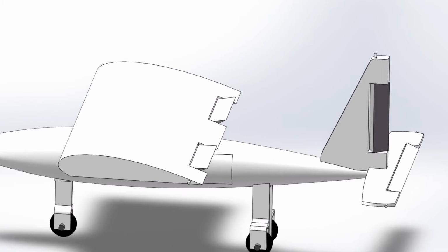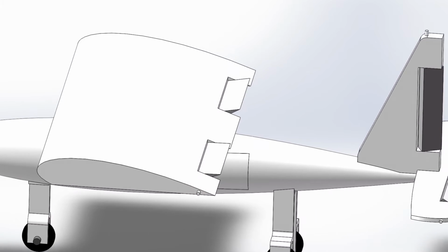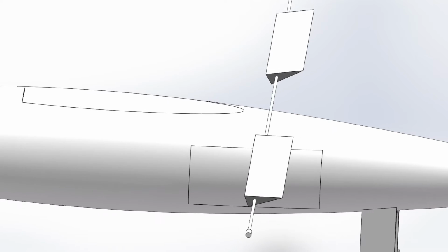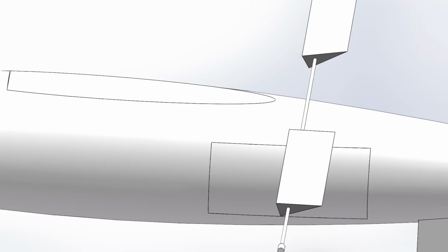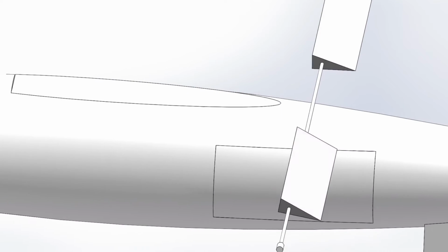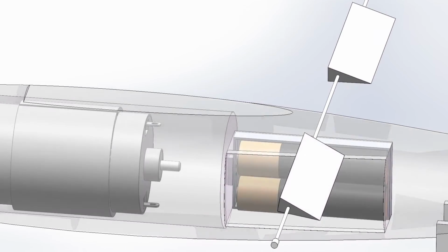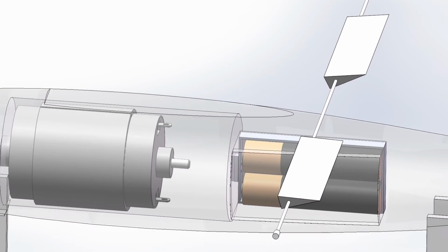Next, we'll take a look at how the plane changes direction. The plane has 3 separate axes of movement due to its 3 separate control surfaces. These are made up of smaller, moving sections on the wing and the tail. To begin with, the aileron system consists of the ailerons themselves and a rod going through the wings and ailerons. Each of the control systems move by rotating the rod using the same battery and motor system as the propellers.